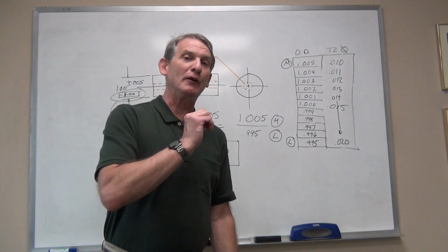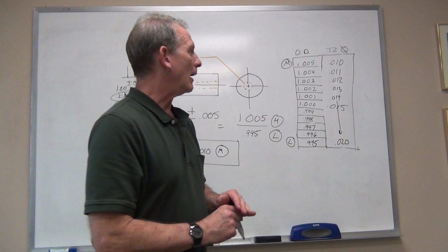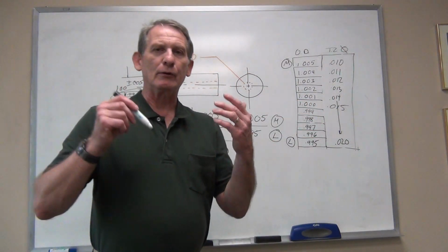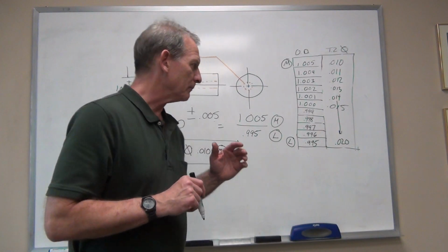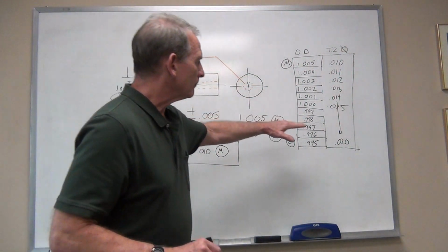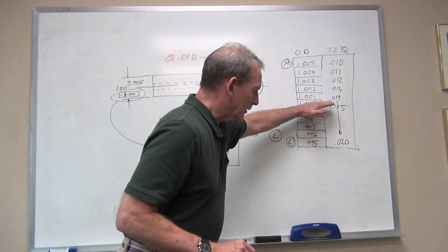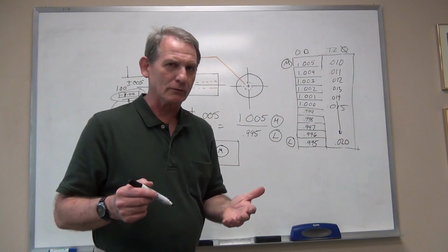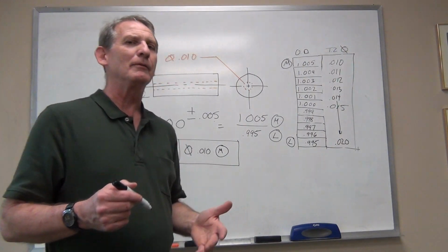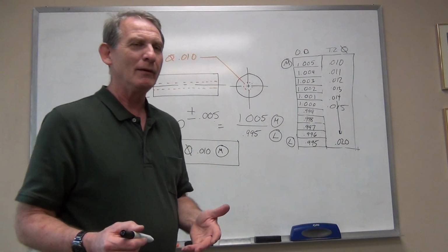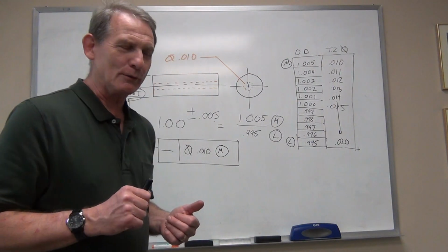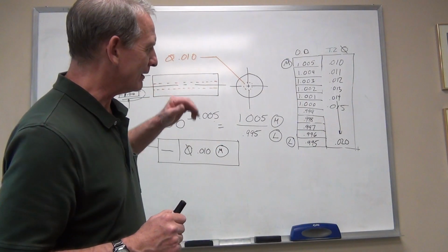So I got a 50% bonus by getting away from the limit and reducing that shaft size. Again, as you head down towards least material condition, the tolerance zone continues to get bigger, but you're getting close to your limit. So you risk scrapping parts in order to get that tolerance zone.